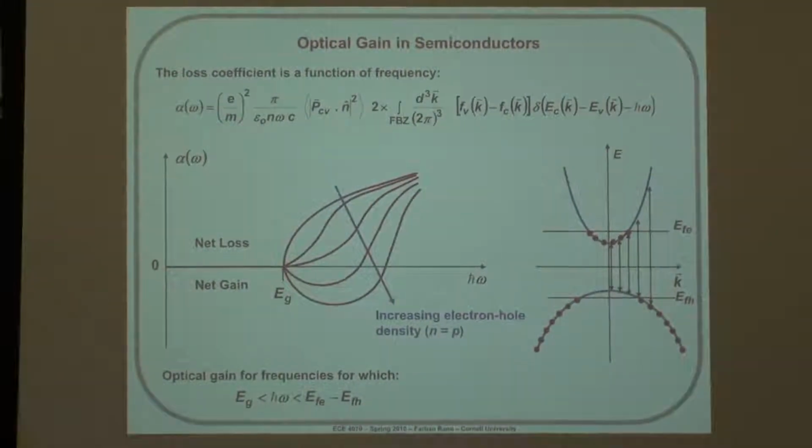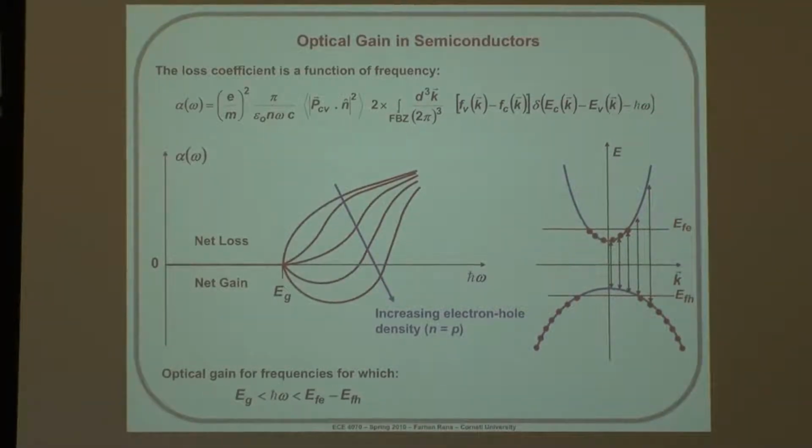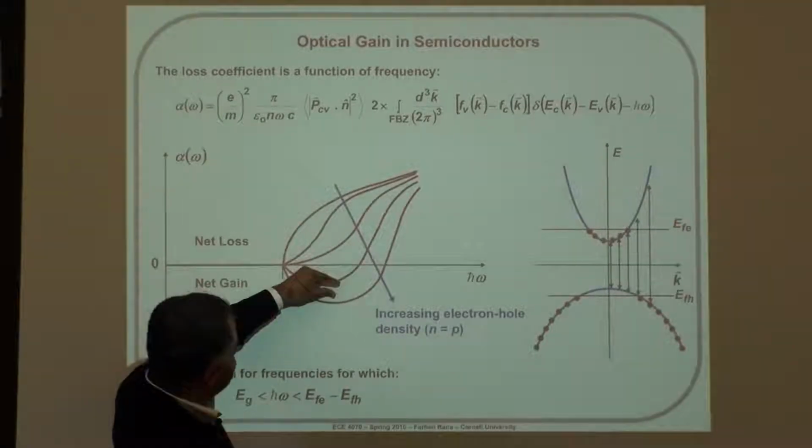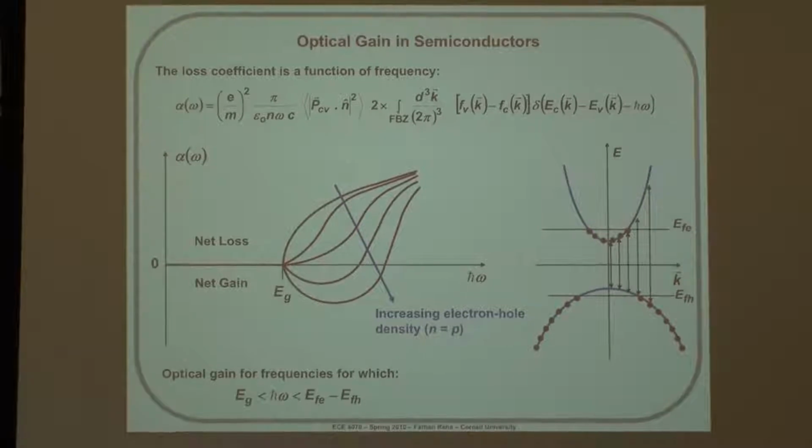Another very interesting effect. Yeah. Is that because you're injecting enough into the conduction band but leaving enough in the valence band that the net gain you'd get is exactly equal to the net loss? Okay. That's right. That's exactly right, because you can see that gain and loss are exactly balanced here. So yeah, right. And then it has some pretty interesting other applications as well.